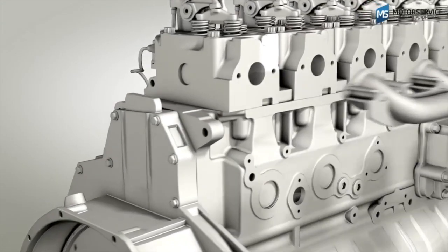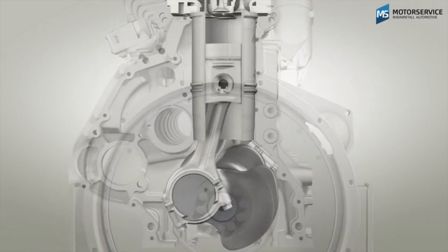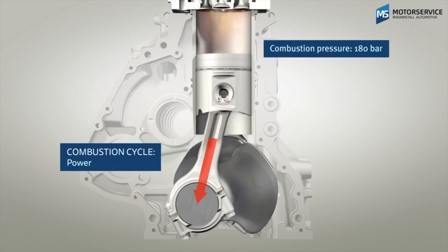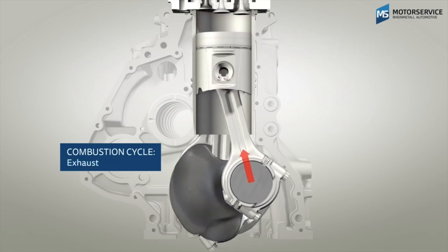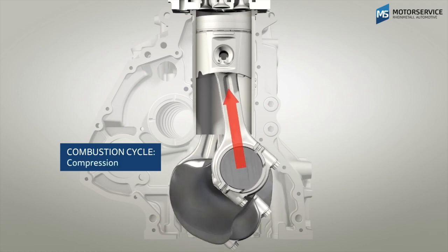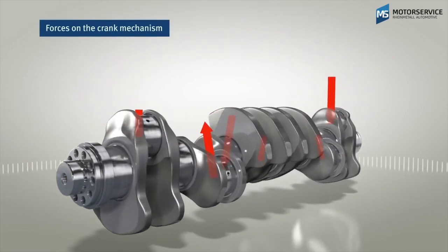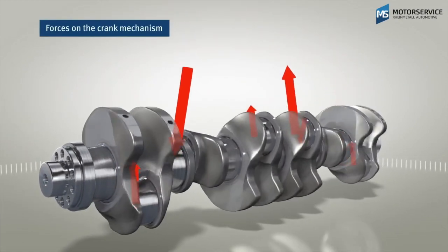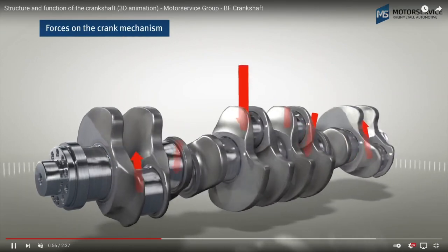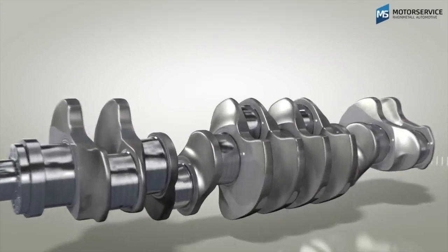As we are in automotive engineering technology, let's take a look at an engine to figure out where journal bearings and thrust bearings are. So as we can see, this crankshaft is moving around the inside of the connecting rod, but it's rotating inside. This means it is a journal sliding bearing as it's supporting radial loads. Then as we move to the side here, to support axial movement of the crankshaft, there are thrust bearings in between these crankshaft lobes here to support the axial loads.